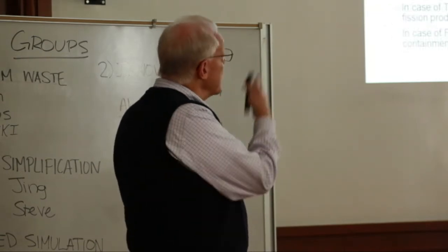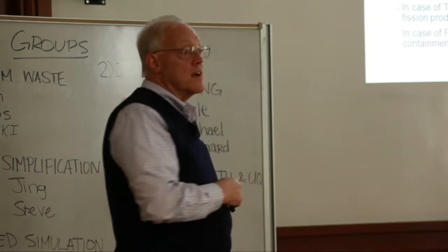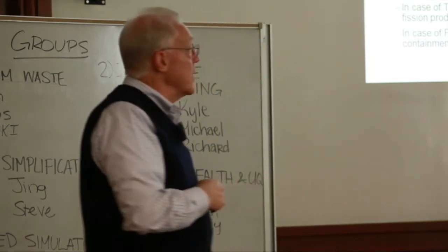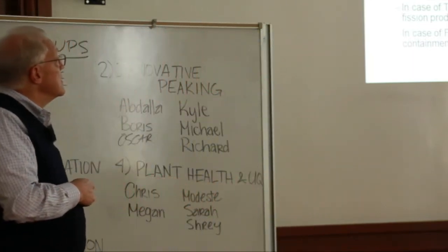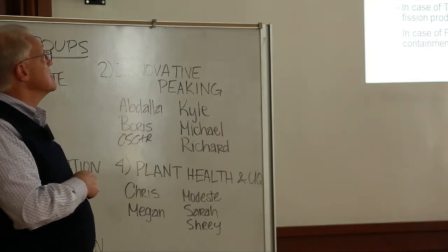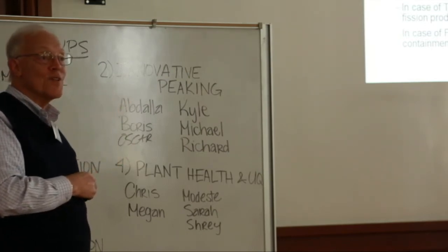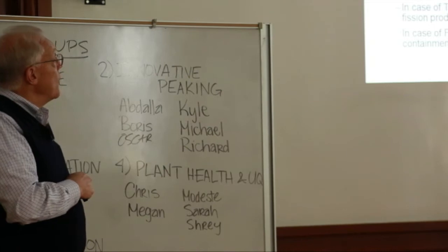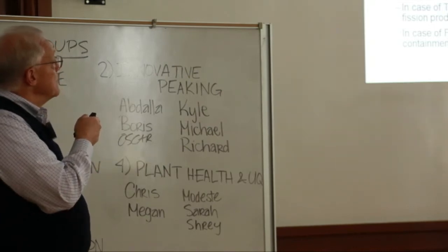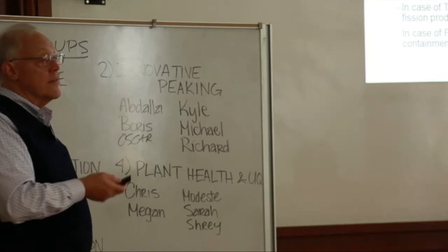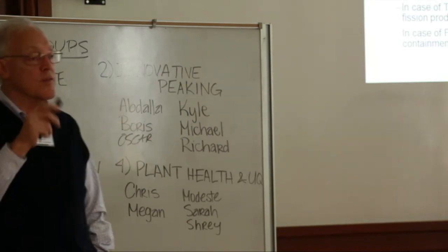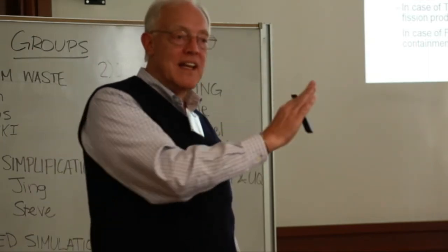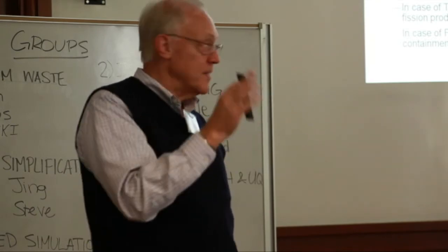Now, the primary hazard, obviously, in our business is radioactive fission products. That's our primary image. And we have all kinds of automated actions in light water reactors to preclude core damage. We have multiple barriers, although one of those barriers is questionable at some times, as we discussed earlier, the metallic barrier. Now, both TMI-2 and Fukushima were obviously the failure of that barrier because of a failure to remove decay heat. It is, and I realize the mix of people's background here. Does decay heat mean something to everybody in this room? All right, I'll let us go on.